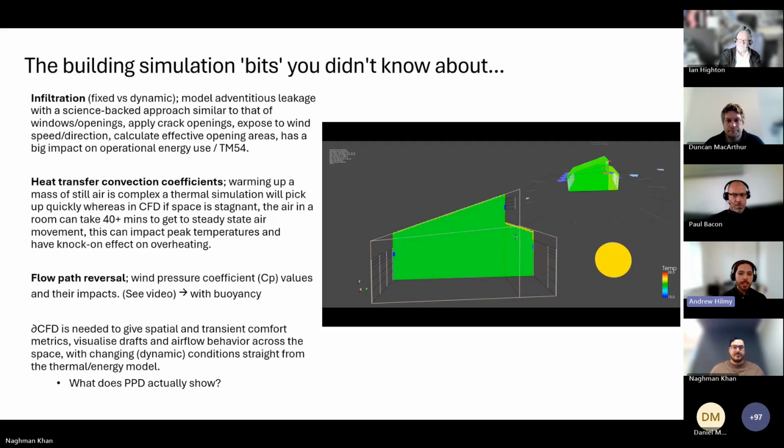You can see that when the wind changes direction, it pushes in a lot of warm air from outside, and it has a really significant effect on the mixing in the space. This is quite interesting because you can help optimize your design here to improve the comfort within the space. For example, when the wind comes from a particular direction, you could improve your design in some circumstances by closing certain windows to prevent certain flow paths from occurring, ending up with a more even distribution of temperatures.